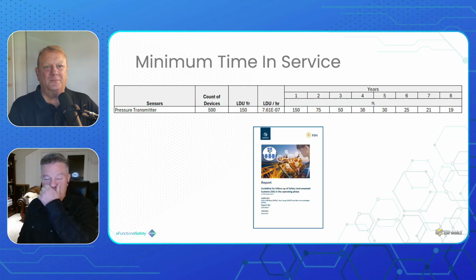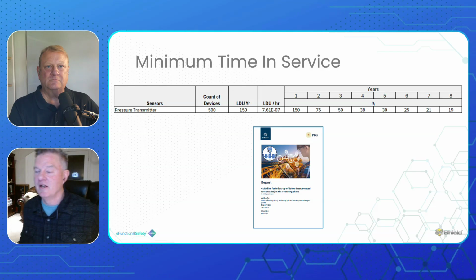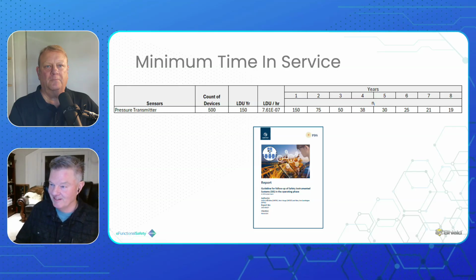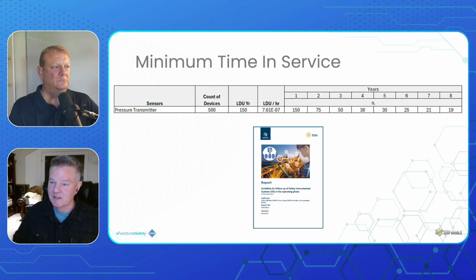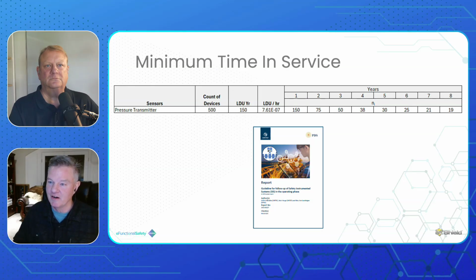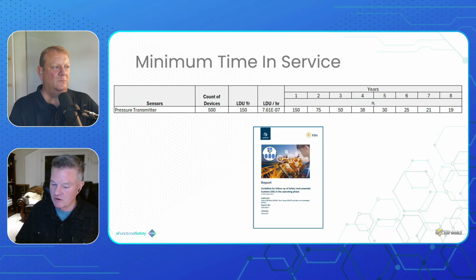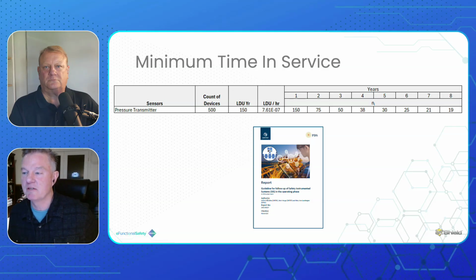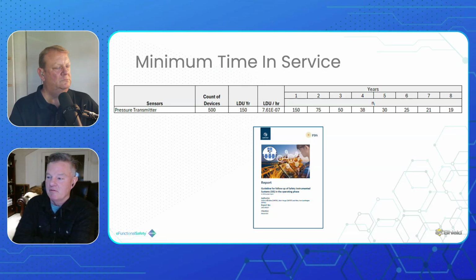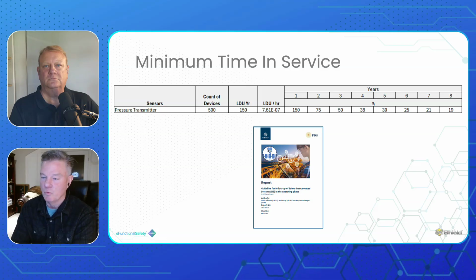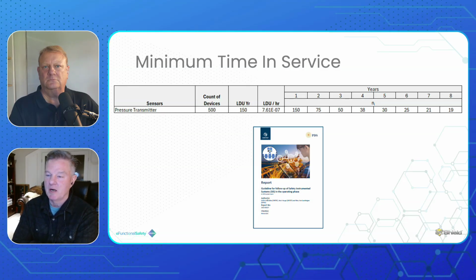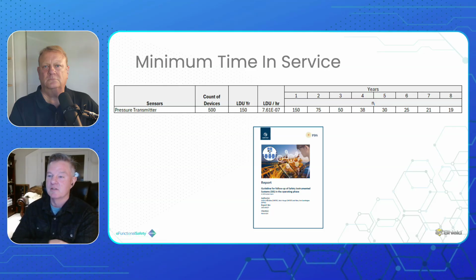Well, that's just it. That's what I'm trying to get at: you're testing these anyway, right? Just get something more than a handwritten chicken scratch with Timmy's initials and a date on it. While you're there, get them to go through that decision tree, find out if it passed with consistent criteria, find out if it failed. Because if you don't have the criteria in place, like a valve, we had valves in Alaska that wouldn't stroke, and they tapped on them with a hammer a couple times, stroked them a couple times, and it passed, and ta-da, it passed.